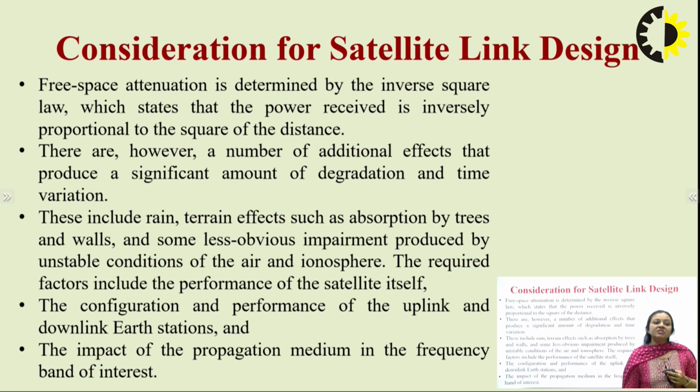Then there are a number of additional effects that produce a significant amount of degradation and time variation. You have to also incorporate these additional effects. You can have the atmospheric effects, you can have the losses associated with the antenna. So the first thing is the free space attenuation, because the path is free space, so you have to consider this. Then the second major parameter is the distance. If I am transmitting at a long distance, power will decrease.